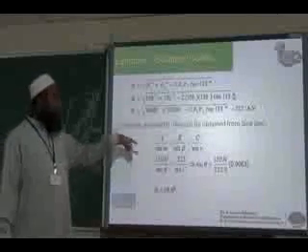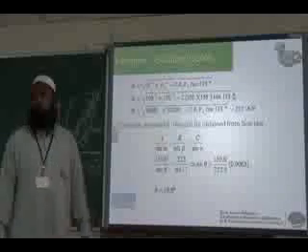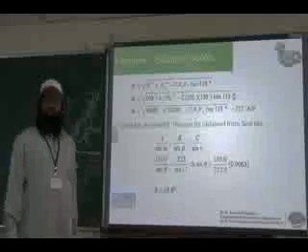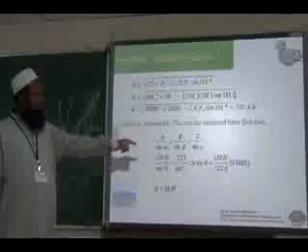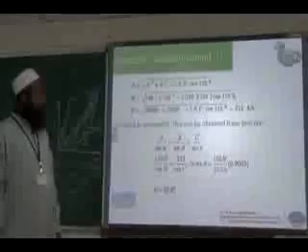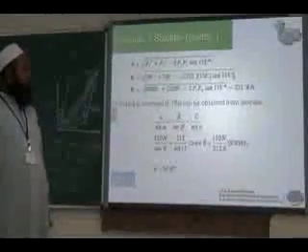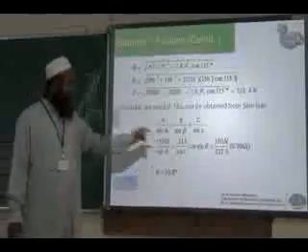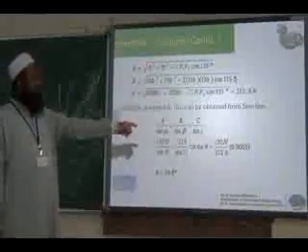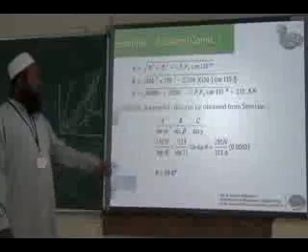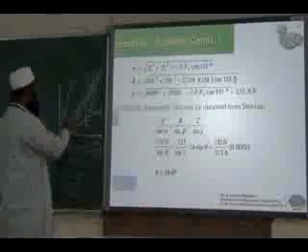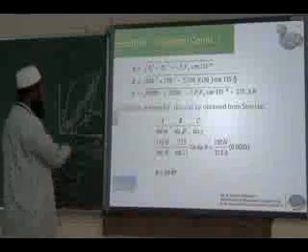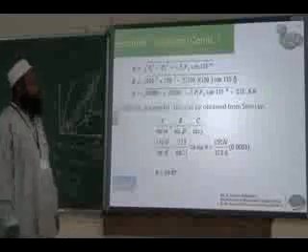We consider A over sine alpha equals B over sine beta equals C over sine gamma. Here A is our force F2, 150 Newton. Similarly, the 213 is our resultant R. This opposite angle is sine 115, and this angle is missing. So we get the answer as theta equals 39.8 degrees. Now that we know this is theta, we can find phi, the resultant angle.